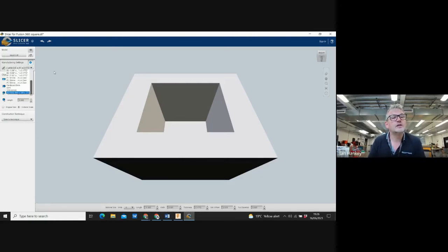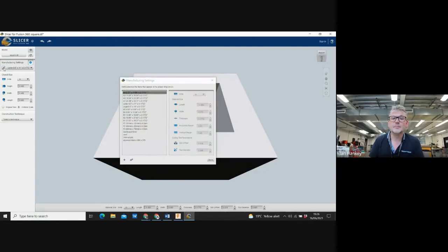Next to it, when it says letter, there's a little pen, which is edit. I'm going to left click on it, and it's going to open up a drop-down menu with all of those different materials on it. And it's in inches, as you can see. What we need to do is add a new material before we start. Now we can choose to add a 6mm thick cardboard or a 4mm plywood, but we probably need both of them if you're going to use both of them.